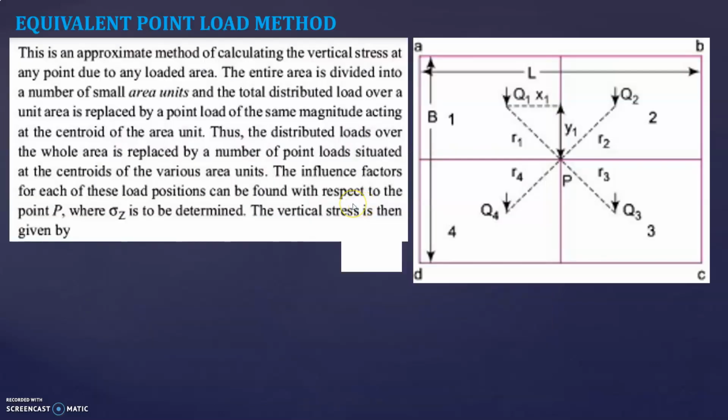Next, let us see what the equivalent point load method is. This is an approximate method of calculating the vertical stress at any point due to any loaded area.